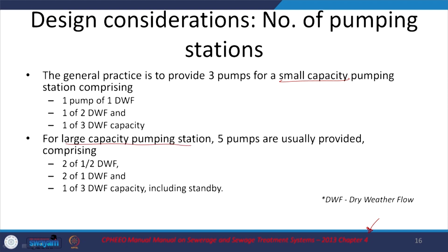So, we have 3 pumps here, and DWF stands for dry weather flow, which we looked at in the earlier session. One pump will have a capacity that can handle the average dry weather flow, one a capacity that can handle 2 times the dry weather flow, and one pump that can handle 3 times the dry weather flow. So, overall 3 pumps with increasing capacities, and here we have 5 pumps for the larger pumping station.